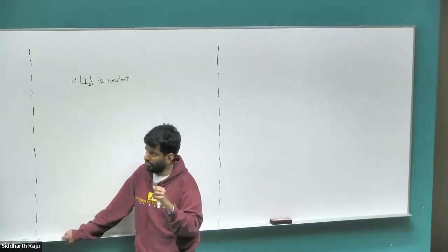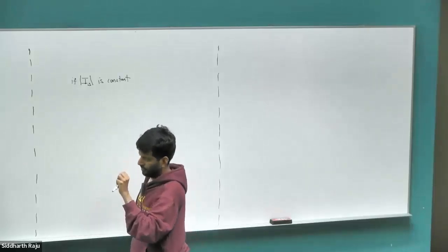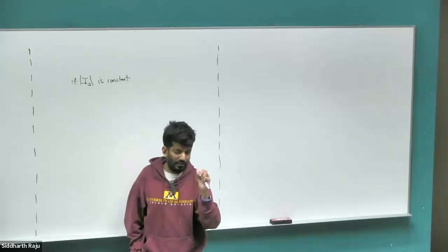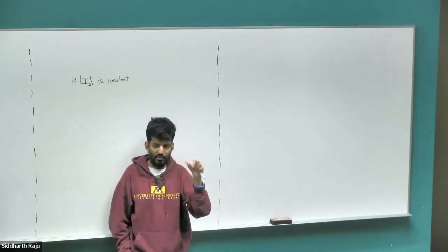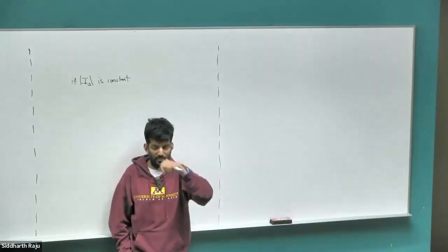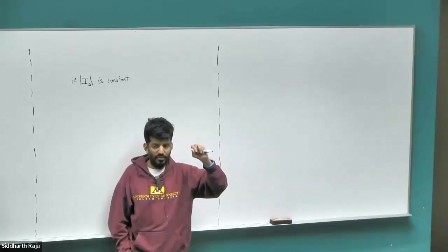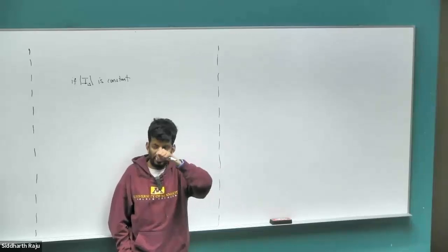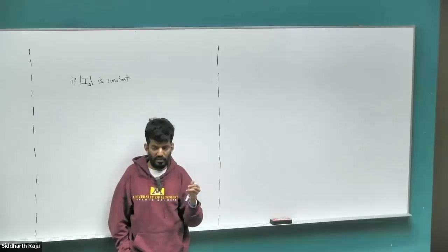So what we instead do is, here is a particularly good insight on what's actually going on. If you look at the space vectors, the phase currents themselves are varying sinusoidally, but the space vector magnitude is a constant for a given magnitude of the input currents. Even though in time the currents are varying sinusoidally, the space vector magnitude is a constant value. And if the input current magnitude moves around slowly over time, then the space vector magnitude also changes, but it's still a DC quantity. You do not get sine waves out of the space vector.